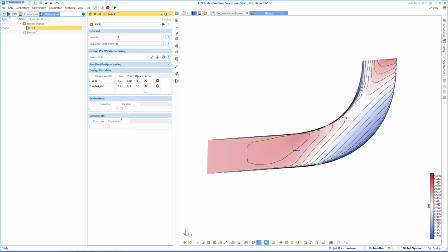And now, which is really important, for the evaluation I have to specify my parameter for the pressure drop. So this eval P inlet. I select this. So this will trigger with each different design the OpenFOAM computation, because it has to be updated here.